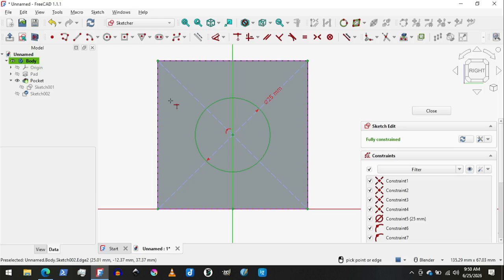Now, I'm not going to select anything. I'm just going to open up, if you look up here, the fillet tool. The chamfer is the other alternative. So fillet, and I'm going to start picking edges. You can see it start to preview. Now, if you're on a slow laptop and it's really slow, you can turn off preview and it will be faster. Okay, so I just pick edges. As I rotate the object around, all of my edges are picked except for the edge of the circle. Now, the radius of my fillet would be 2.5, not 1. So 2.5. I hit OK.